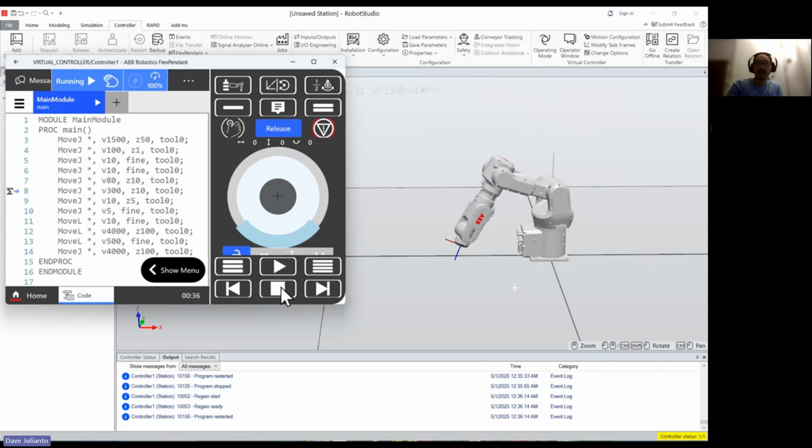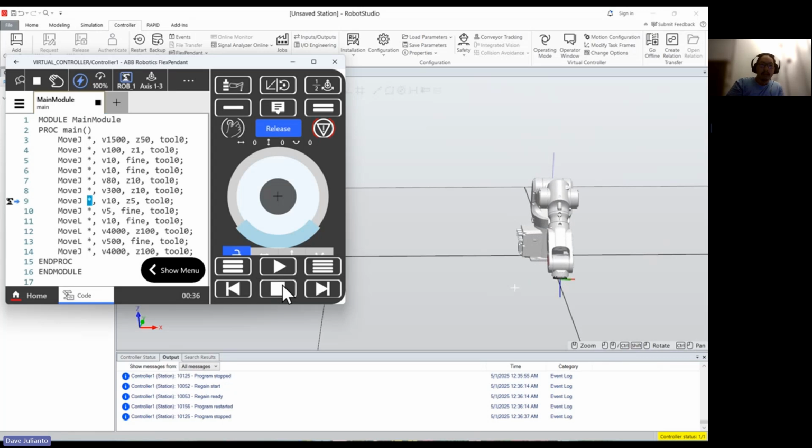Yeah, we're doing it with relatively faster speed. And then we try to make the robot swing toward the screen with a move J. Then let me hit pause. So then we move the fifth axis and then the fourth axis. So it appears that if the robot is applying an operation on a different line, the gripper would be facing diagonal to the part, so it would appear like this.